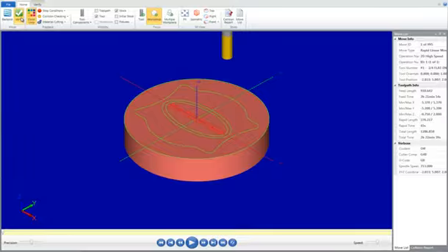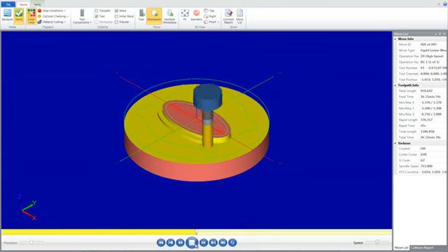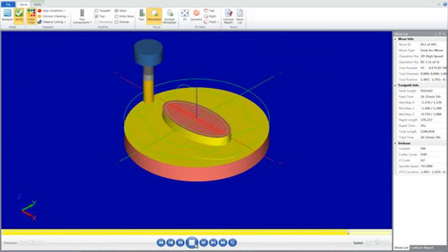As you verify tool paths, Mastercam displays additional information such as the X, Y, and Z coordinates, the path length, the minimum and maximum coordinates, and the cycle time. It also shows any collisions between the workpiece and the tool. Ensure that the following settings are enabled: Tool, Stock, and Workpiece. You can now press the Play Simulation button. Your part will appear as shown. You can now exit Verify.